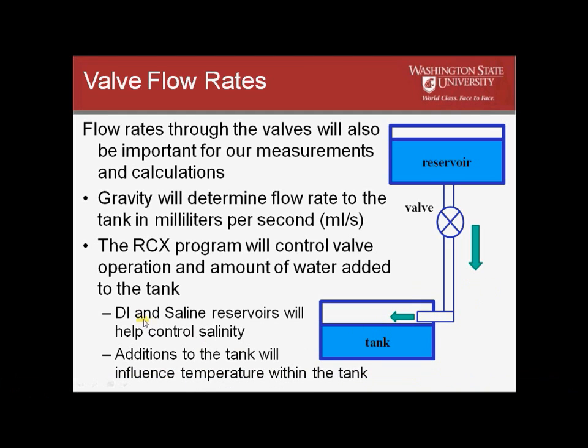And so the DI and saline reservoirs or tanks that we'll be drawing water from will help us control the salinity, and additions to the tank will also influence the temperature within the tank. So the system becomes a little bit more complex because as we add water, that temperature in the tank will also change. Of course, the purpose of adding the water is to modify the salinity to the desired level. So the two control systems will have to work together.